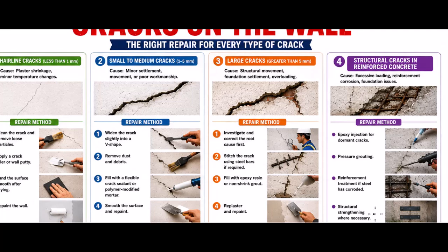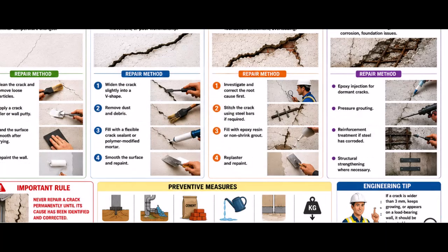Another effective way of handling this is to break down the wall to the foundation, from where a fresh footing and column is planted, taken straight up to support the cracking wall. So this is another way of solving the cracks, especially when they are serious and they are from the foundation level.